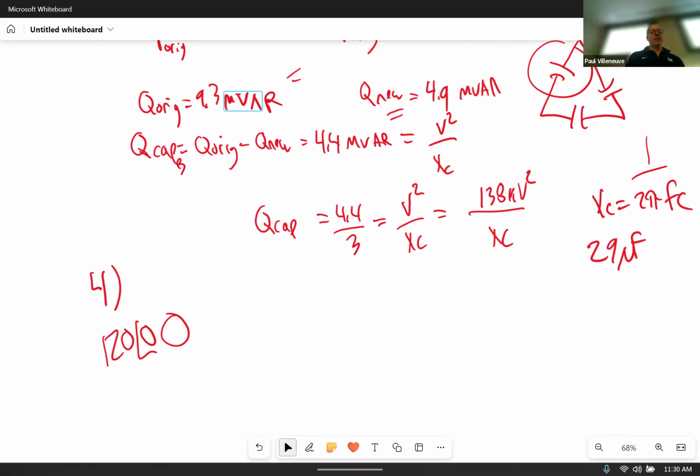Secondly, 120 is the RMS. Should I multiply that by square root of 2? Yes or no? How come I had a lot of tests that did though? When I multiply by square root of 2, what am I getting? I'm getting a peak value. That's not what we do AC circuit analysis in. That's why I used 120 volt, because when you plug in your outlets, it's a 120 volt outlet. That's RMS, not peak. So you shouldn't have needed the square root of 2.